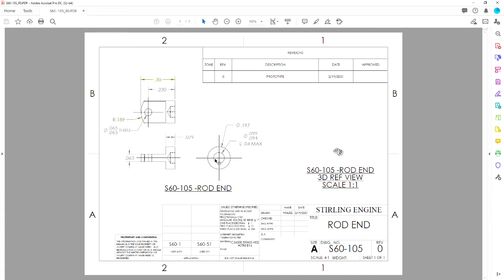And we come back and use the hole wizard for the end hole, and we could use it for this hole on the tab, or we could use extruded cut, either way. We would want to use the drill hole wizard so that we get the cone point that's allowed for that particular hole. It's allowed to be a blind hole with a tip, drill tip there.